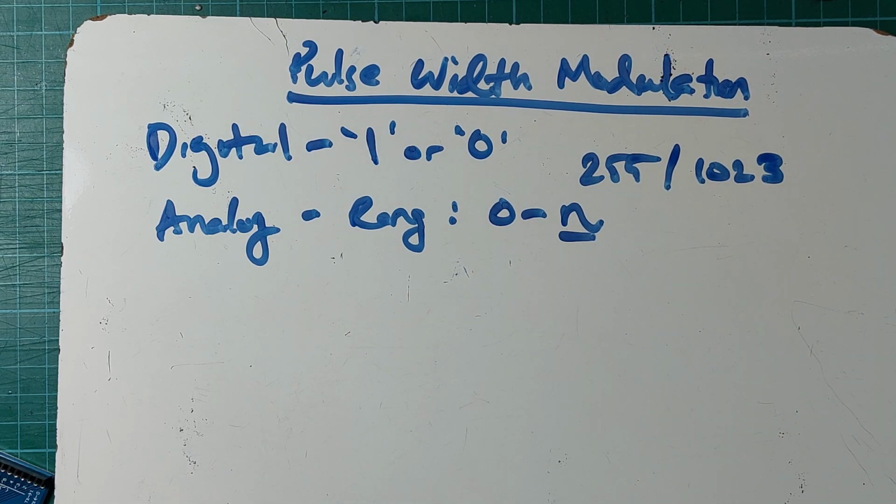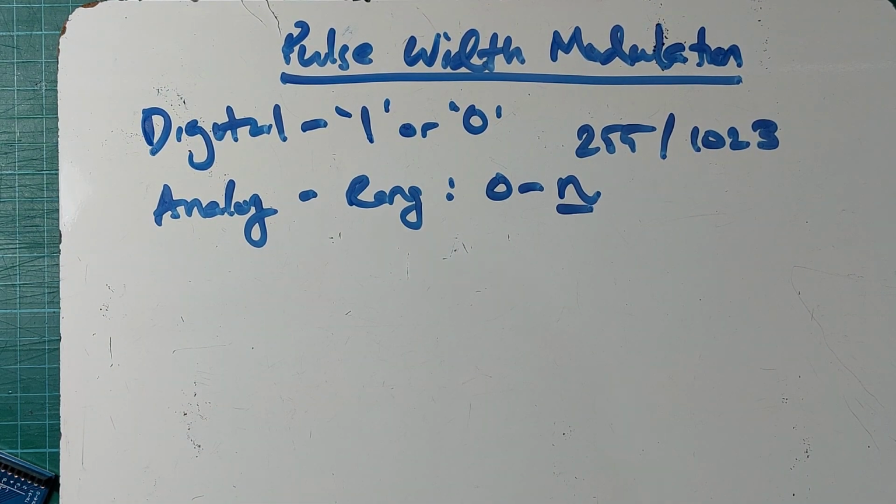So if I have a digital output, I can only output on or off. If I have an analog output, I can output a number, like some value, say a voltage value between 0 to 5 volts. Perhaps I can output the intensity of sound, the speed of a motor, stuff like that. These are all analog values because they are not just on and off. They have a range to them. So how do we achieve an analog output using digital values?